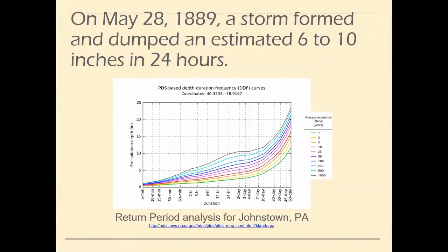One of the main things that you learn in water resources engineering is this idea of a statistical take on rainfall and other natural variables. And so we have this return period analysis that essentially shows you how rare it is for different kinds of events to occur. And you see rainfall of different durations, different depths, and then again, that return period in the colored lines.